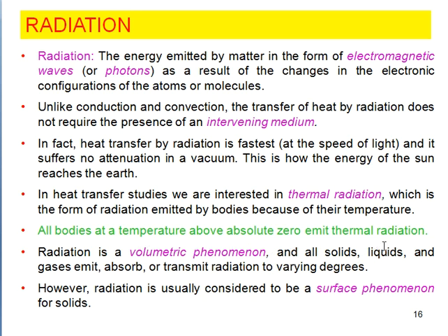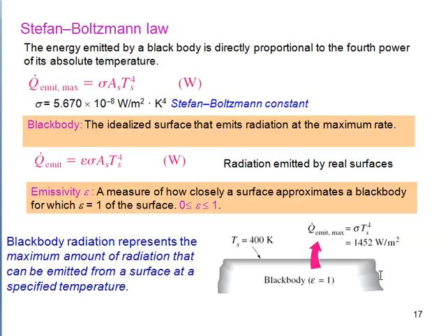Radiation is a volumetric phenomenon, and all solids, liquids and gases emit, absorb and transmit radiation to varying degrees. However, radiation is usually considered to be a surface phenomenon for solids. Only from the surface does radiation heat transfer take place, and within the body there is no radiation heat transfer.